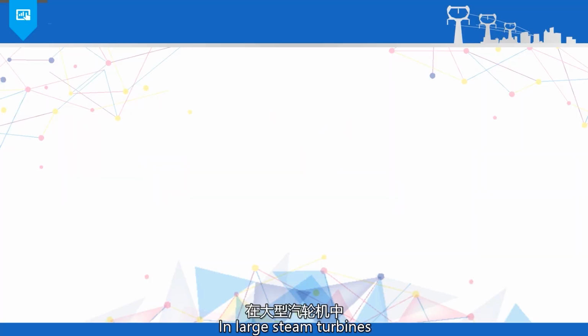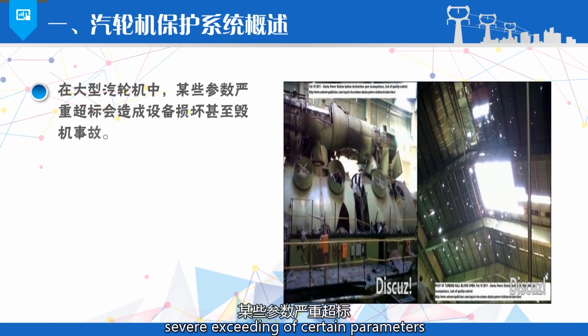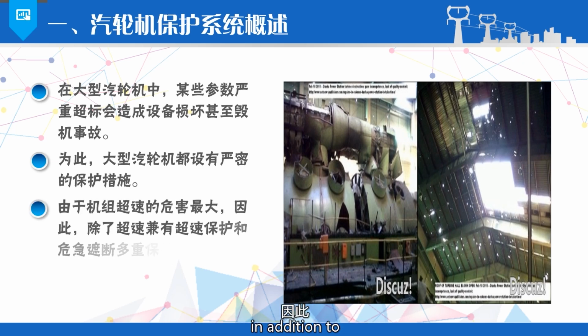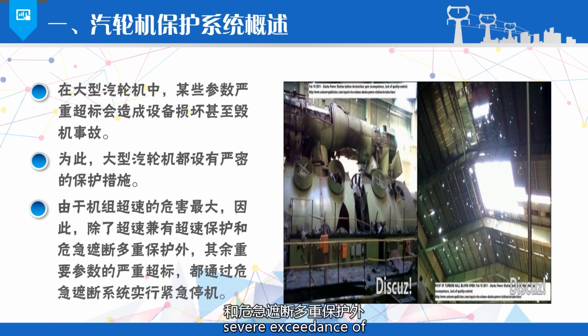In large steam turbines, severe exceeding of certain parameters can cause equipment damage or even accidents. For this reason, large steam turbines are equipped with stricter protective measures. Due to the greatest harm caused by unit overspeed, in addition to overspeed protection and multiple emergency shutdown protections, severe exceedance of other important parameters is handled through the emergency shutdown system.